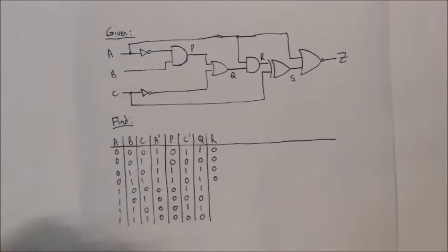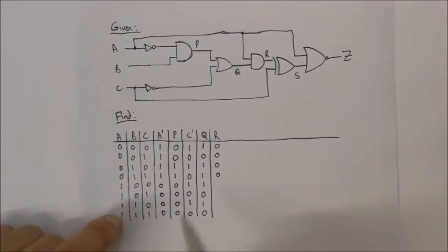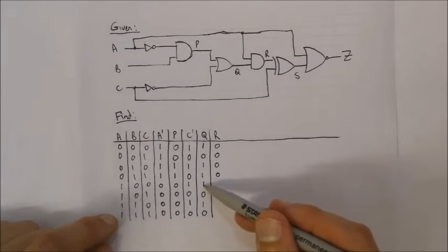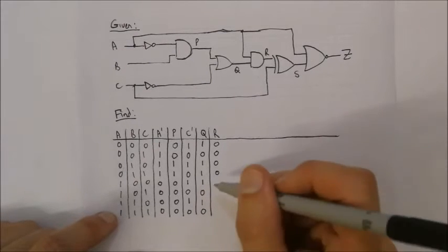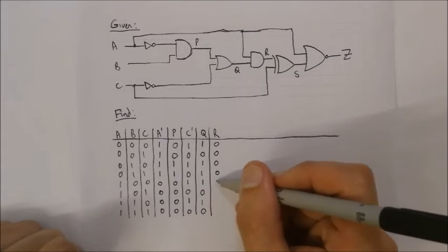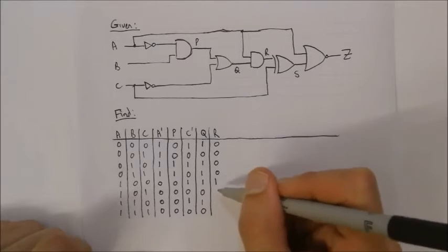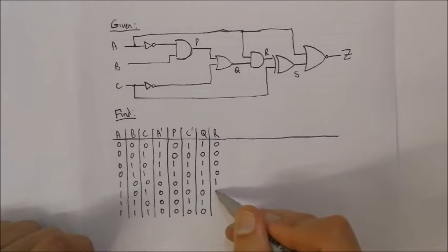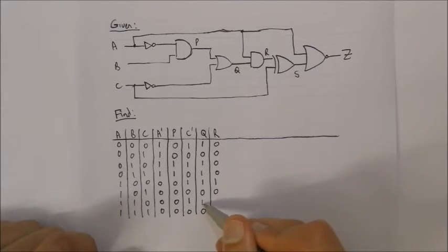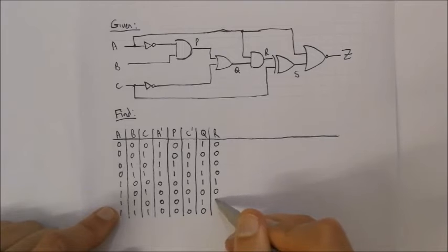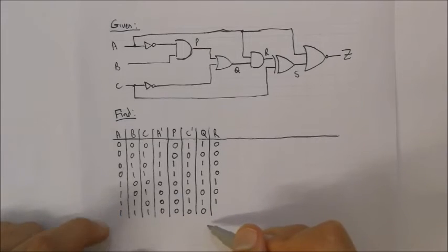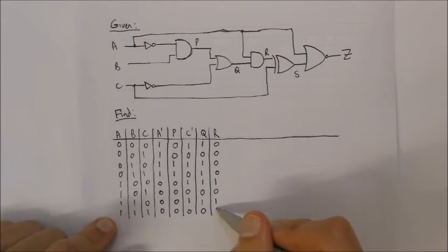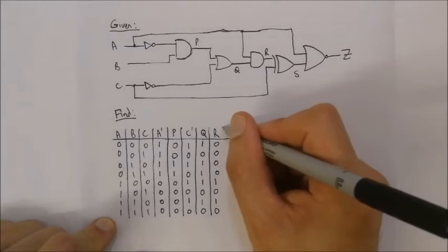Over here, we've got A that's equal to 1. So we can basically look now at when is Q equal to 1. Well, Q is equal to 1 over here. So that would mean that both A and Q is 1. So an output of 1. Q is a 0 over here, which means that the output would be 0. Q is 1 over there, and A is 1, so the output would be 1. And over here we've got A was 1, Q is 0, so the output would be 0.